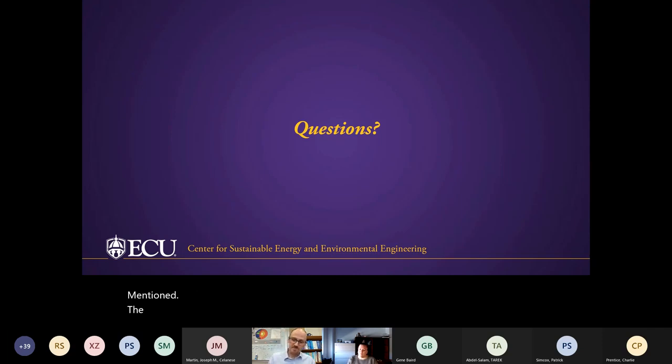And Miguel mentions PFAS, removing PFAS from wastewater treatment plants. That's definitely a hot topic that Miguel brings up, and I gave a seminar all about PFAS a few months ago. We were focused on membrane processes like reverse osmosis, and we were thinking a little more about drinking water treatment. If you have PFAS in your drinking water and you need to remove it, and you're using something like reverse osmosis, you're going to have that PFAS in your residuals.